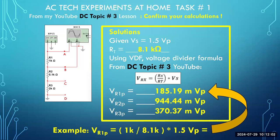Now, if you don't get these answers, let's go ahead and review how this is done. I spoke the formula a moment before we went to the pause, but now I have it written down so that you can review this. Take a look at the example at the bottom of the screen, you will see I'm looking for a quantity called VR1 peak. So voltage across resistor number 1 in peak form, all right? So as I look at the formula in the white box, in order for me to determine this voltage, I'm going to start off in parentheses, Rx over RT.